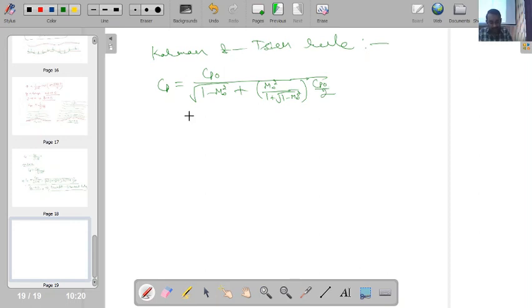Okay, and now if you make the comparison between the three rules, say this is Cp, this is M infinity, so here say I am having values minus 1.8, minus 1.0, say somewhere over here minus 0.2, and this M infinity must vary from 0 to 0.8 because we are talking about subsonic flows.